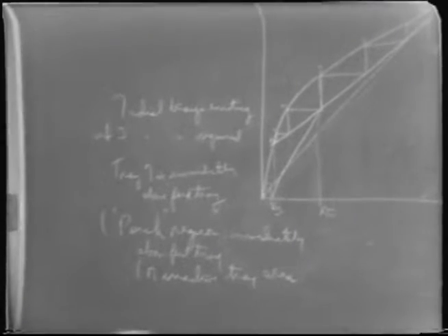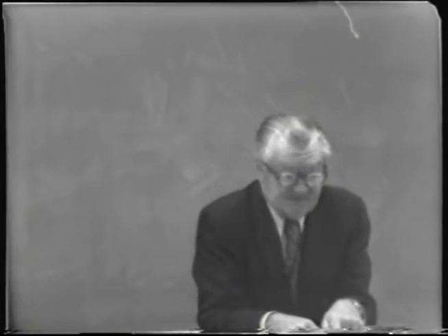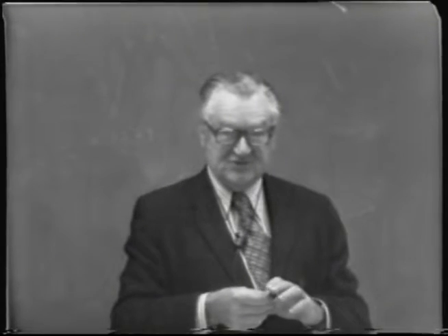Do you understand what I've tried to illustrate here? This is a condition that's very frequently met with in distilling columns used here in California, particularly when they're making beverage brandy, as we saw down at the Bear Creek Winery, where they were just drawing off a side stream at 170 proof. I don't remember now how many trays above the feed, but they had some 42 trays in that fractionating column, in the rectifying section of that still.